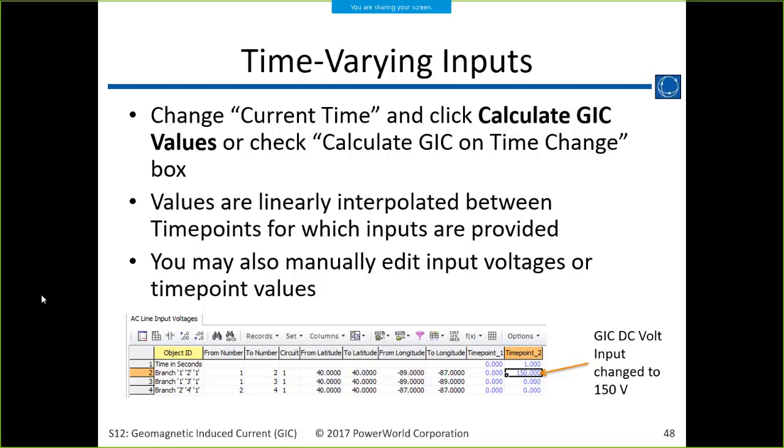Is there an option to, or is this how it's done? The Q loss factors that are calculated, and there's the maximum Q loss depending upon the direction of the storm. When you're doing the combined AC solution, does it use the maximum or just what you had specified? No, it's the current. It tells you the maximum so that if you wanted to change the orientation to the maximum for studying the whole system, you could do that.